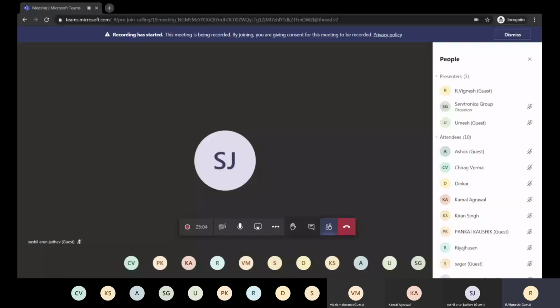So let's say this is a component we want to create a BOM for. I can just quickly go, and the best part is you will always be working with the main assembly. You need not worry about the child and sub assemblies. You can just click and pick the main assembly, and say open. It takes a little bit of time based on the size of the component, and it quickly generates your report in Microsoft Excel format.